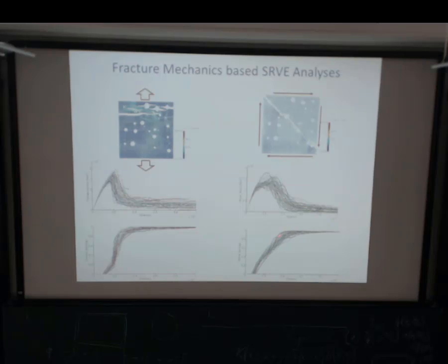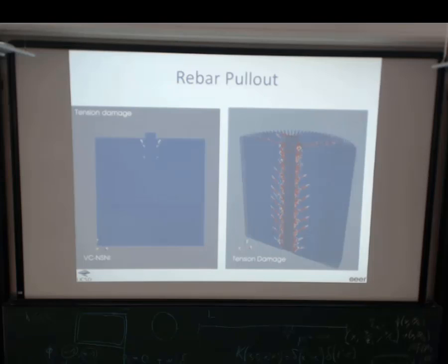They behave similar, but different microstructures does give you a different damage curve. And now you can use this for structural scale computation. One can now introduce stochastic representation of the material model, since now you can extract stochastic properties from here, and then you can have a material model that is stochastic, okay, if you choose to do so.